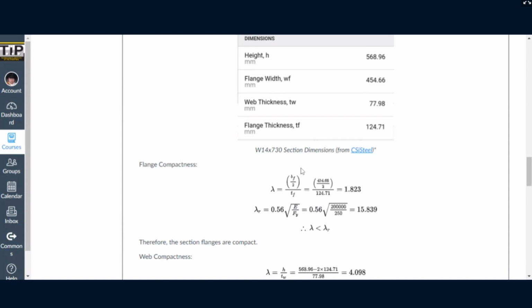So it is important that in the parameters right here, the units must be consistent so that they cancel out, because the width thickness ratio is unitless. So if you use SI, SI only. If you use English, English only. The same answer will come out here. So these formulas are applicable for both SI and English, no? That's the beauty of our formulas in steel. It is applicable whether the system of units is SI or English. Unlike in RCD, if you change units, your formulas change. Okay? For steel, we do not have a problem with that. As long as your units are consistent, it's alright.